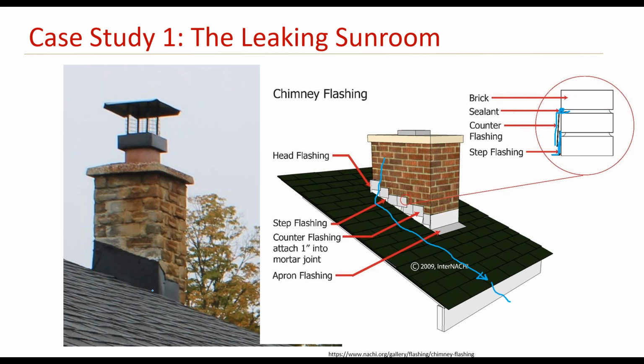The problem that we have here is the contractor decided to just put the flashing, wrap it around the chimney, and ignore any counter flashing, ignore applying the flashing as a step flashing, and put a couple of screws here and there, and then some sealant, took the money, and called it a day.